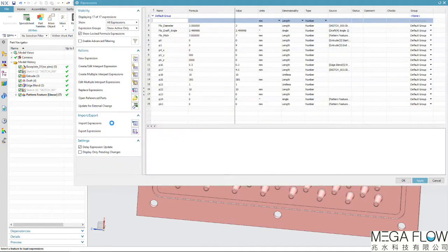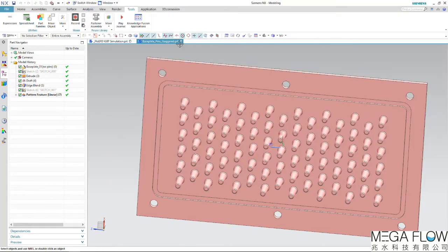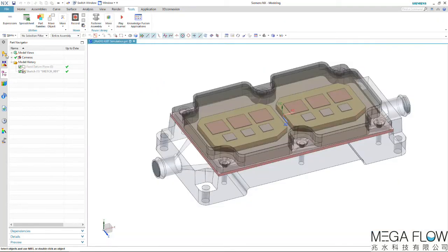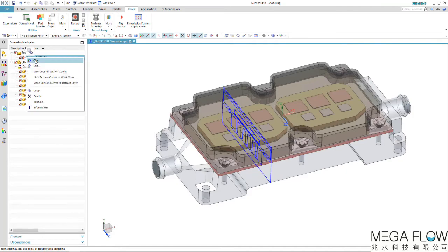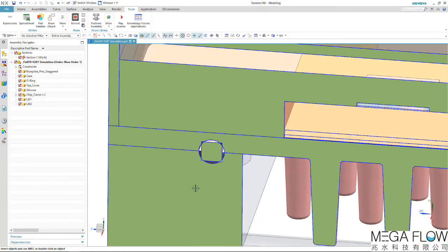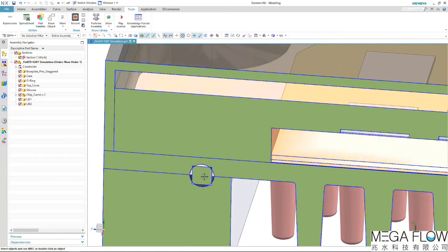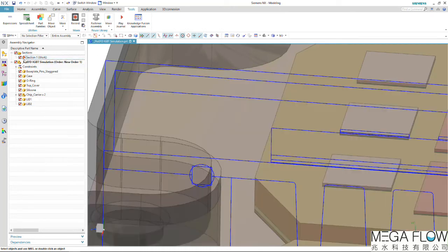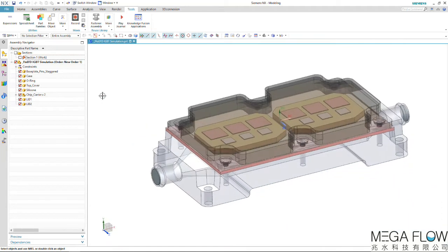Looking at the NX expressions, we can see there are 3 parameters controlling the heatsink pin width, draft, and pattern spacing. The model has been designed this way with later optimization in mind. Jumping back to the main assembly and taking a cross-section, we can see there is some geometrical overlaps between the parts around the O-ring and silicone potting compound. FloEFD has no issue with overlapping and dirty geometry. There is no need to spend time fixing this, just be careful with material priorities.